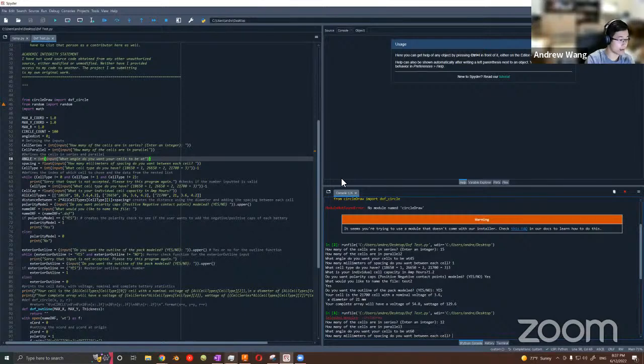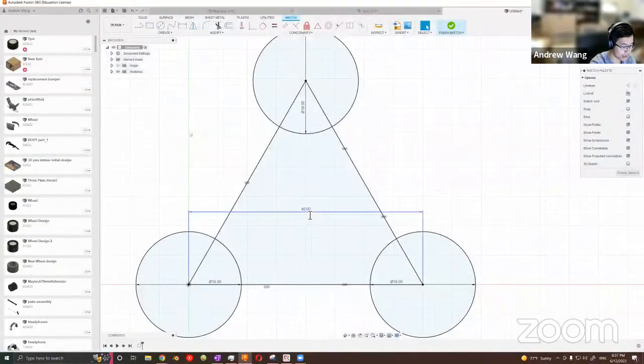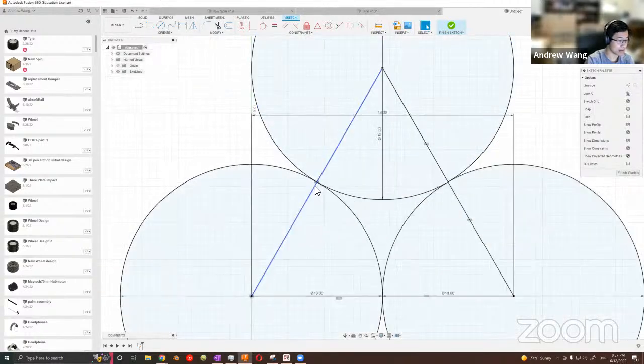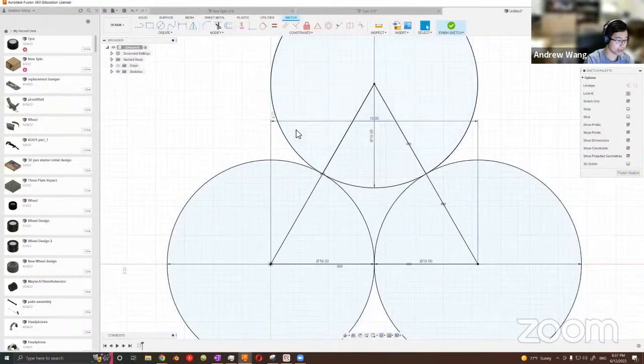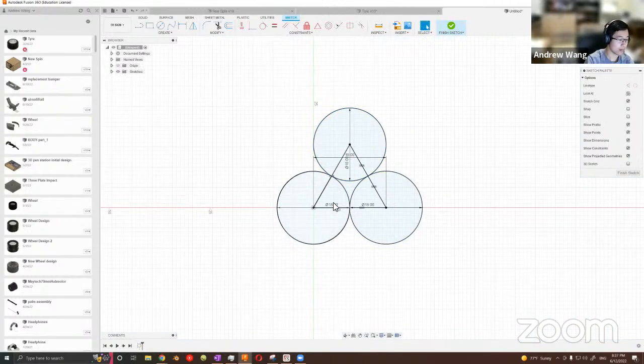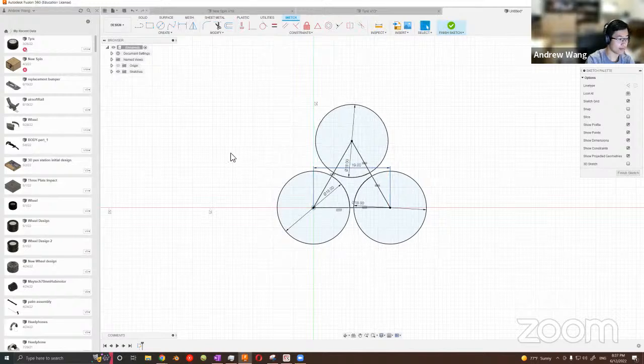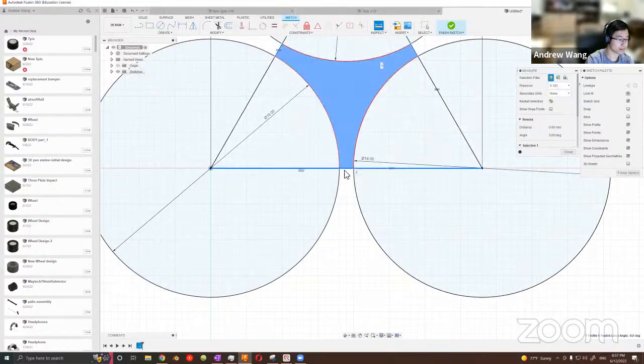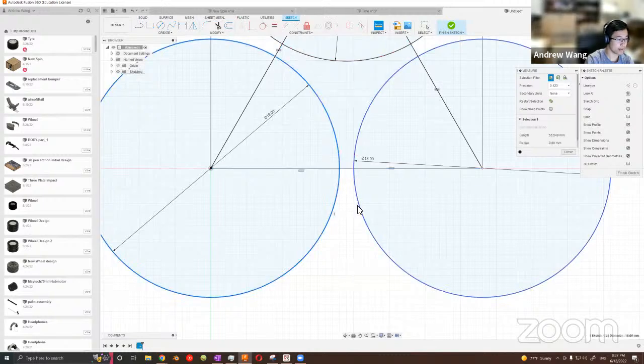like over here, the closer the cells are, say this is 18. There we go. These are literally on top of each other. There's no area for the casing to hold them together. So what I need to do is make it 19. So if the distance from here to here is 19, the distance from circle to circle is 1 millimeter.